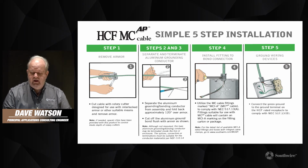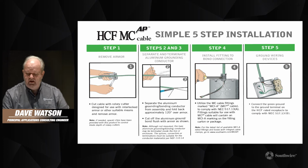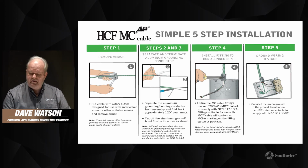Step 4 is to install the fitting to the box with the snap fit fittings. That's as simple as just simply pushing it in and snapping it into place very fast. Then step 5 is to ground the wiring devices. So you may need to install a pigtail from the device over to the box for proper bonding.